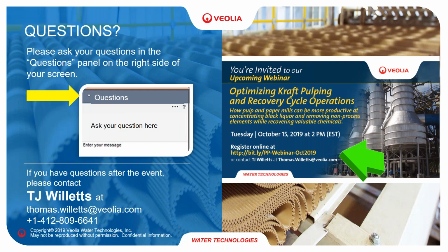Yeah, so the easiest way to use the gas is just to send it to the boilers. This is what most of our clients do. Of course, sulfate is often present in wastewater, and sulfate will reduce in an anaerobic environment to sulfide, and part of that will end up in the biogas. So often we need to clean the gas before we send it to boilers.